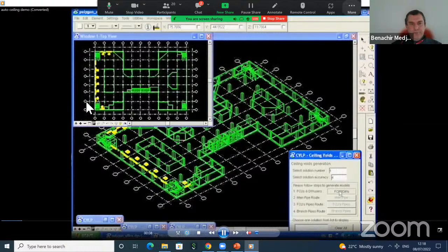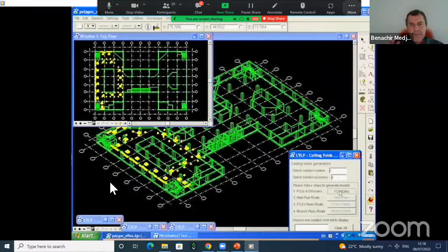After several inputs, the system generates in 3D, calculating first using rule of thumb the number of fans, diffusers, etc., and then locates in 3D space all the fan coil systems and diffusers automatically as a first stage, dividing this building, which is H-shaped, into 3 rectangular zones. I will come back to that as it is very important to divide any complex geometry into much simpler ones to solve the problem.